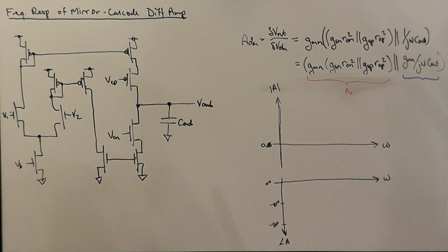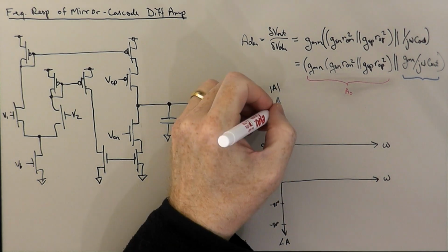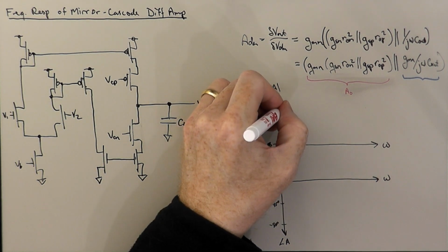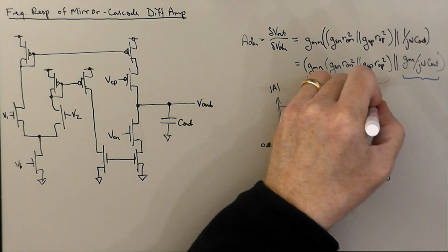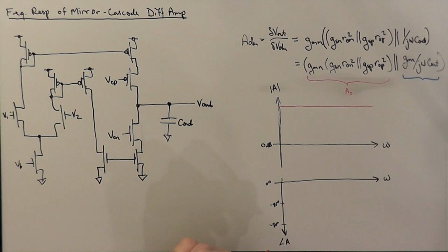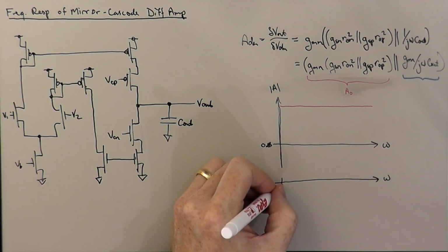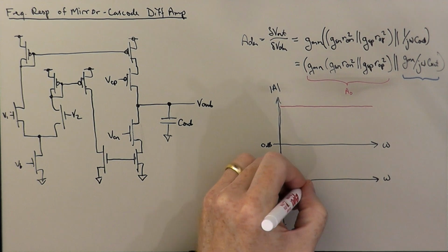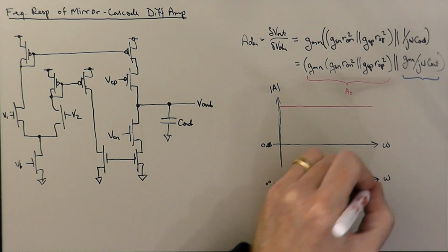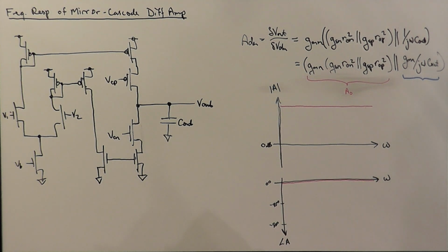And so let's plot these two components, the blue one and the red one, as a function of frequency on the Bode plot here. So A0 is some high gain up here that's constant at all frequencies and has a phase angle of 0 degrees. It's a positive real number. And so it's got some magnitude expressed in dBs at 0 frequency.